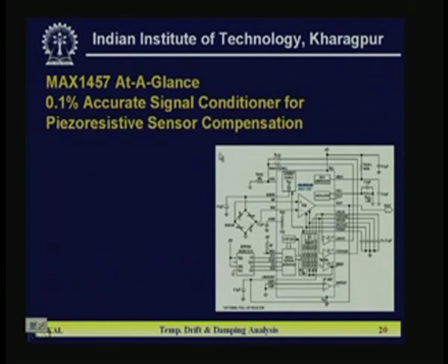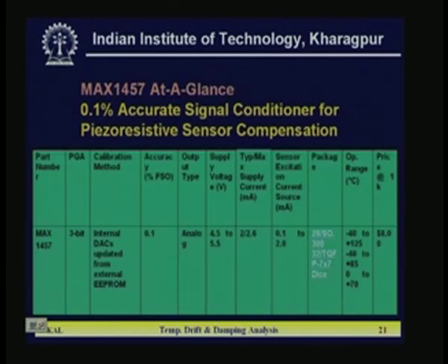Then here the temperature variation, all other variation due to either the piezoresistive coefficient or elastic, whatever it is, that variation is reduced to 0.1% by a lot of innovative circuit techniques, and that chip is available, and people are using the chip in a multi-mode packaging sensor, and at the same time at the output they are connecting the chip, so that temperature compensation will be done.